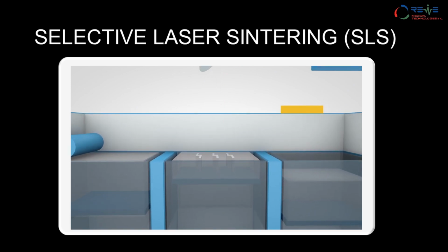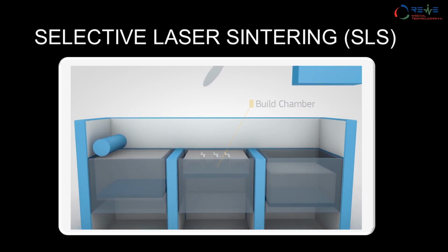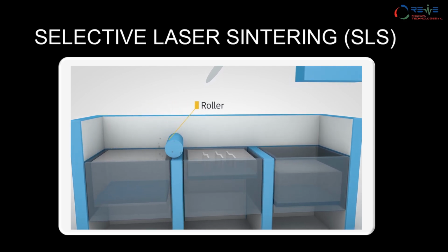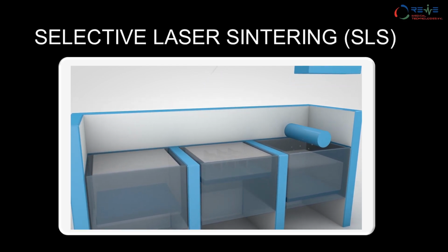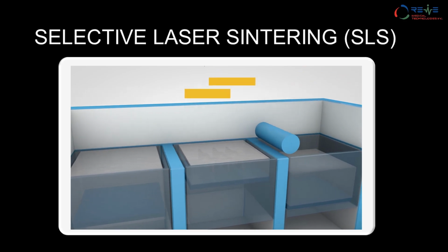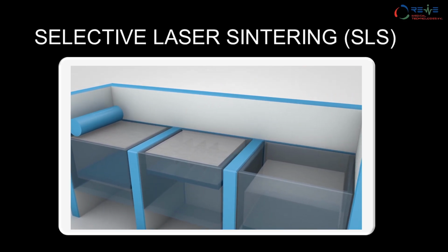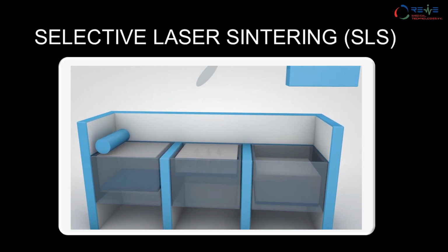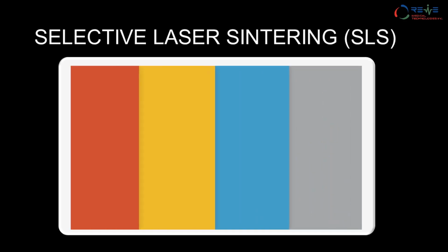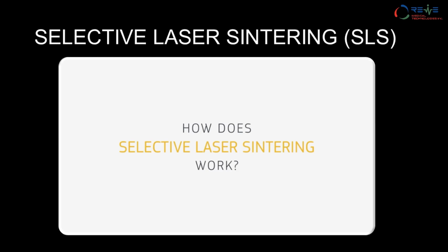In the selective laser sintering process, there is a main bed in which the laser is curing the material, and layer by layer there's a roller that removes the excess material from the top and then adds more material over it as well. Layer by layer the platform moves down and you start getting the 3D print made downwards. You saw it in the video as well. So this is another effective process.